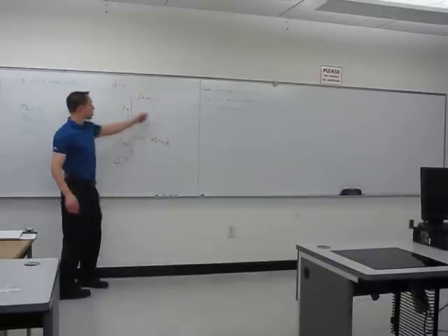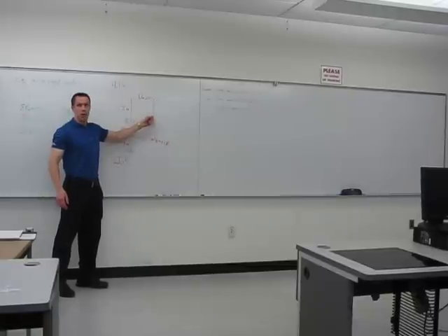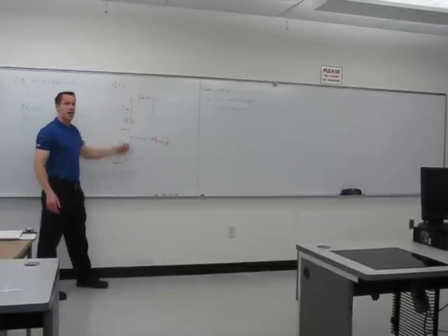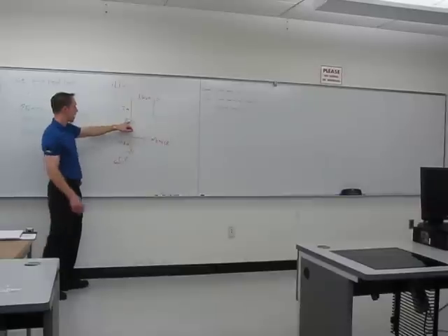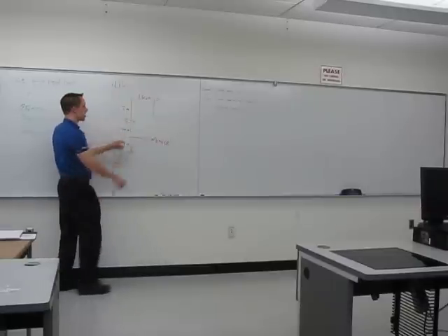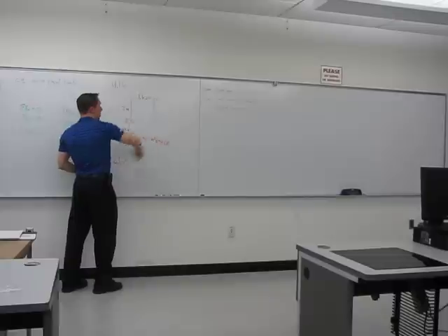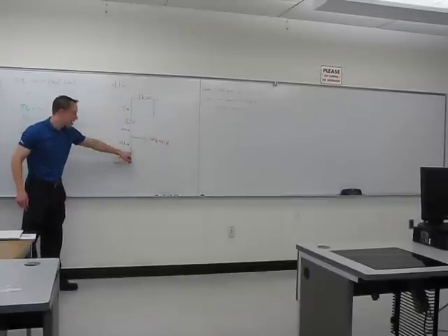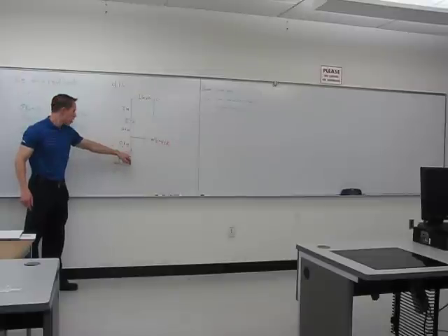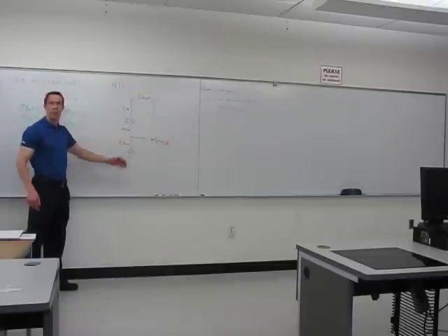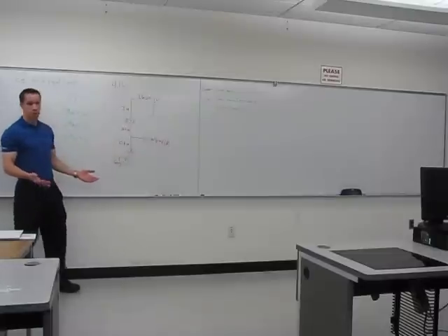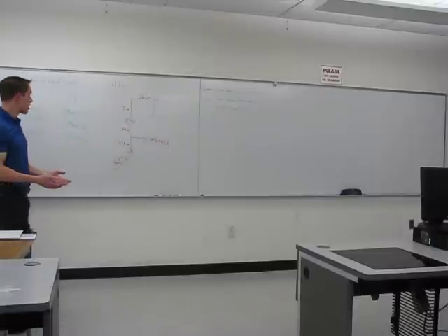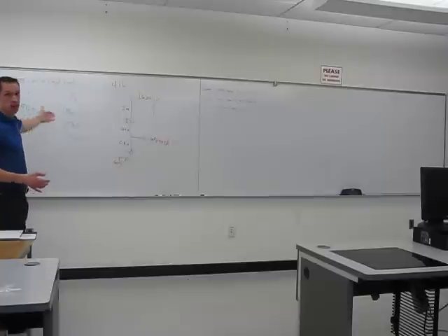So the spring force is pulling down, which, if that were the only thing acting on the rigid body, we would then have some rotation around this point C. Pull down on D, we would get this thing rotating in a clockwise kind of way. But down here at the bottom at A, we have this little wheel, which is up against this big wheel, preventing that rotation from happening. So the net result is everything is motionless. So it's in equilibrium, which means these equilibrium conditions are going to have to hold true.